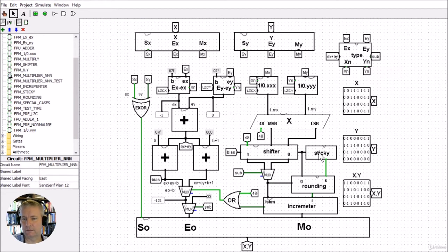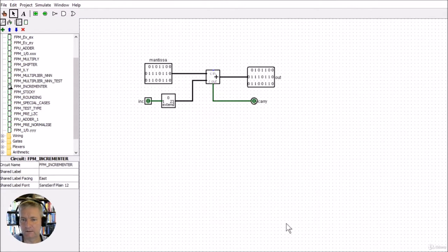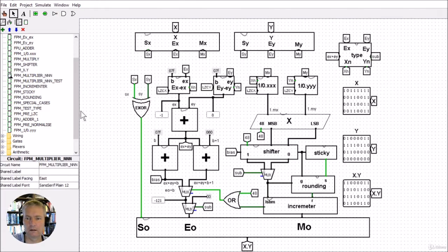So the rounding section would come out, we'd have worked through the rounding, and we'll either have a high or a low bit, and if we had a high bit then it would round the value that we have here, but in this case here you can see that we've actually got a low output, so there isn't any incrementation here, so there's no addition of an extra 1 there due to rounding, and there's no carry bit coming out through there either. So it means there's no path coming through here to the OR gate. And finally we get our final output down to the mantissa.